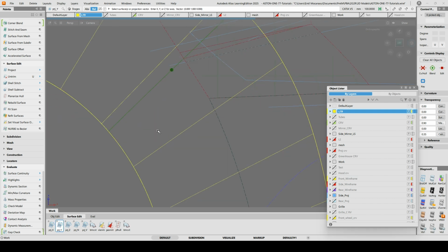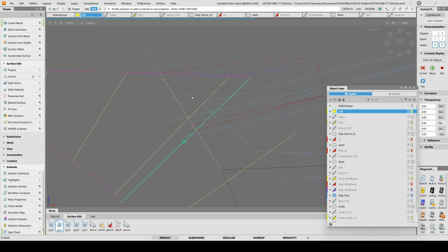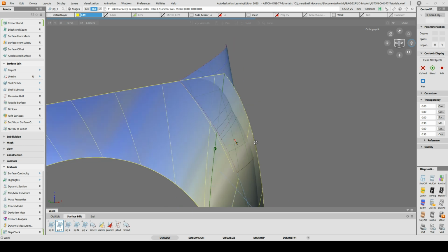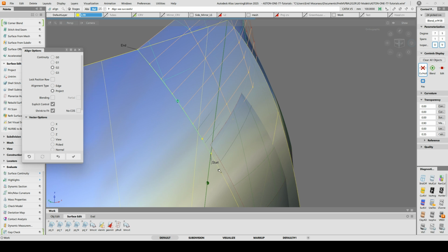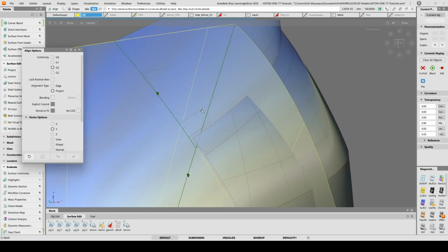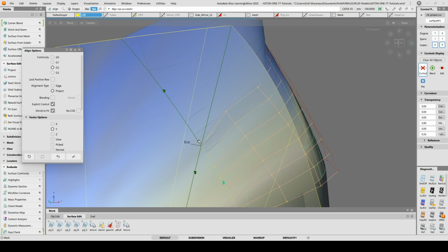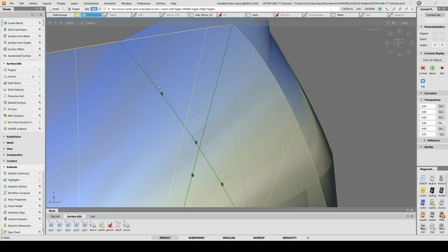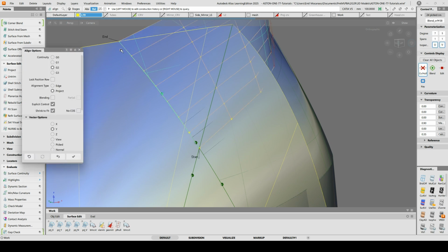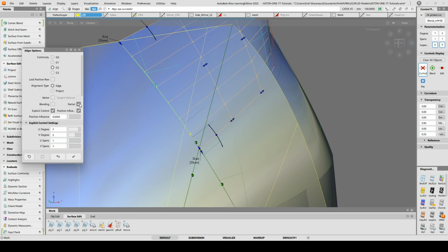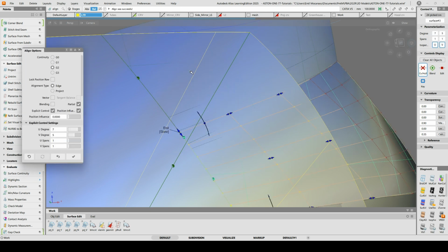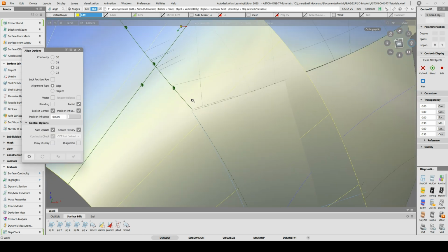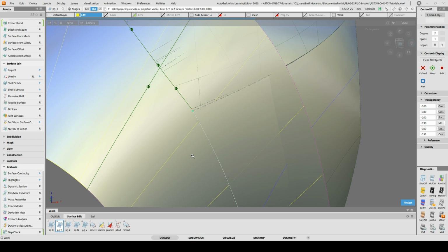So I'll project onto these two surfaces this curve here. It's going to be edge alignment onto that curved surface. What I'll do, I'll hit this one onto that and that as well. This one gets aligned there and there as well. Make sure you click partial. And now we project to that surface this curve.